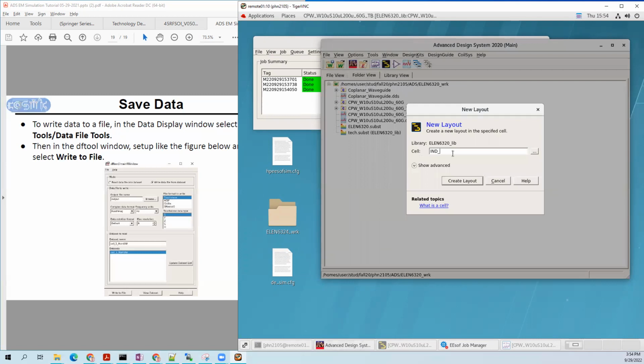The thing is, most of the layout shapes are going to be defined in the PDK. So in Cadence, you can have an option of which inductors you want to use and the dimension of the inductor as well. But in this course's PDK, we don't have that luxury. So if you want to have an inductor in your schematic, then you have to draw your own inductor. But in here, I'm going to quickly show how I would draw an inductor.